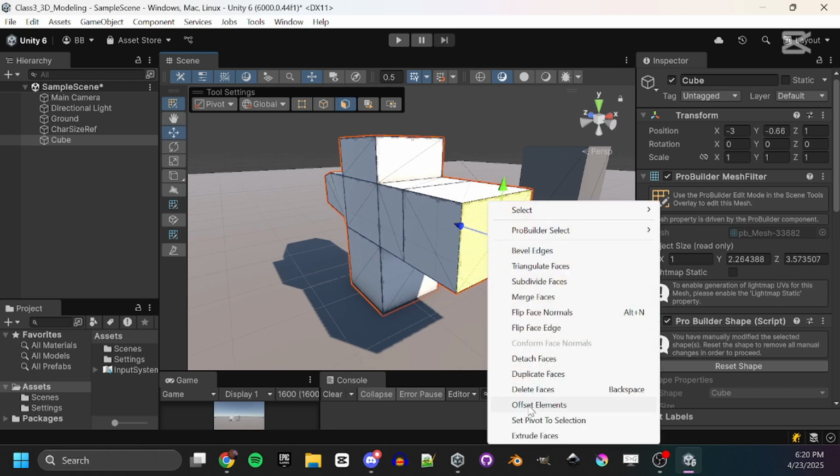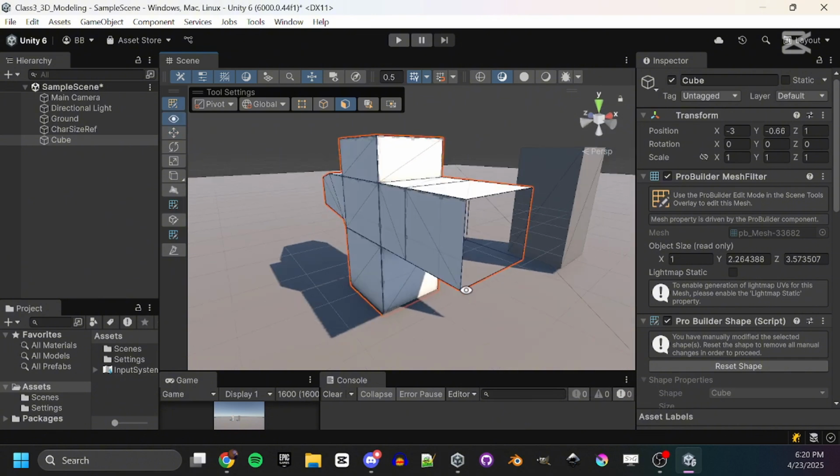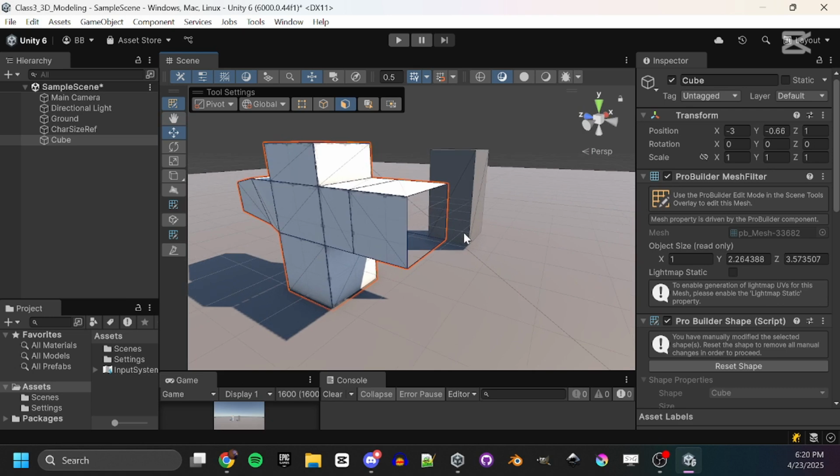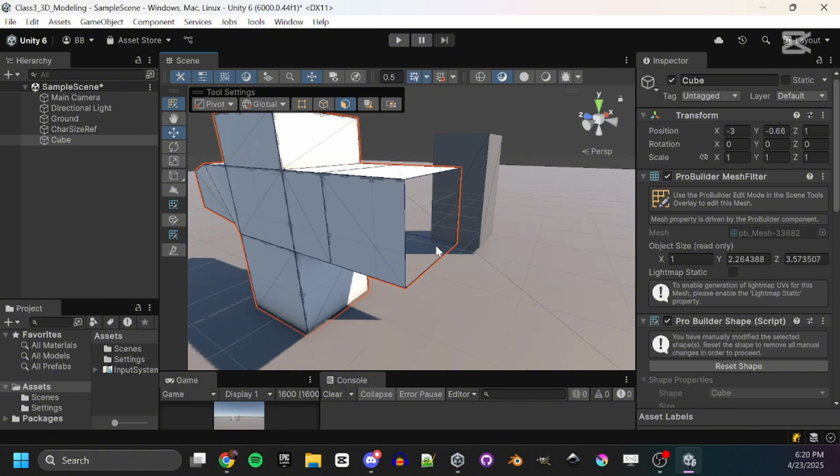So for example, if I were to delete this face, you see I now have a gap here. And then I could have something else, select edges or faces, and then bridge them. Although you're starting to get into the kind of thing that's going to be better to do in Blender when you're doing something at that level of complexity. But it is completely possible to do that.